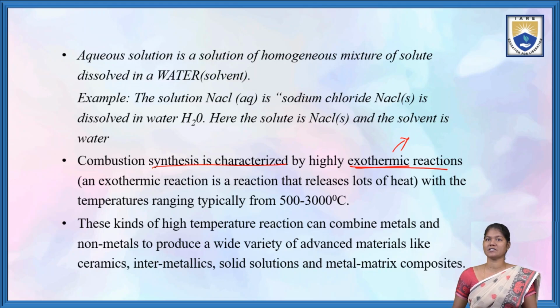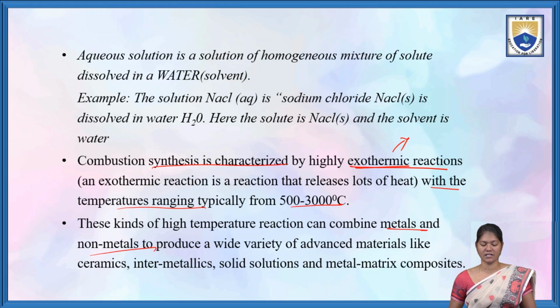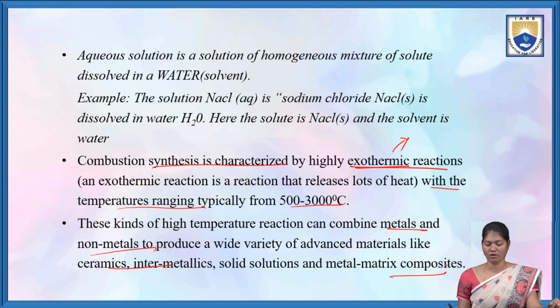So combustion synthesis is characterized by highly exothermic reactions with temperatures ranging typically from 500 to 1000 degrees centigrade. This kind of high temperature reaction can combine metals and non-metals to produce a wide variety of advanced materials like ceramics, intermetallics, solid solutions, and metal matrix composites.